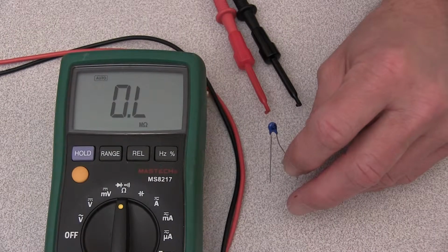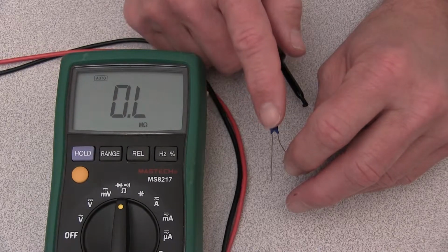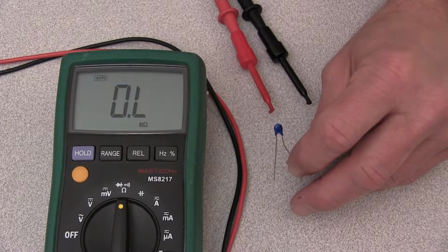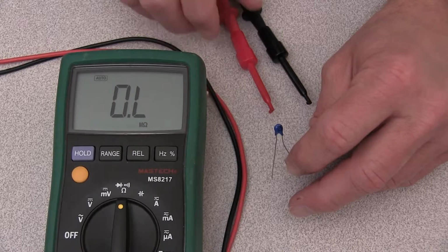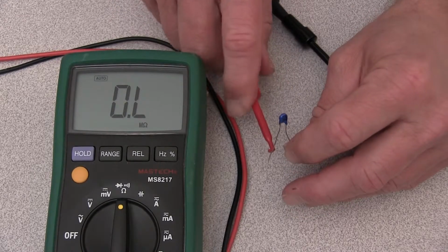This is a thermistor. If the temperature here changes, the resistance of the gauge changes. This sensor is what's called a negative temperature coefficient, or NTC thermistor. That just means that the thermistor resistance goes down as temperature increases. The first thing I need to do is characterize a thermistor. I want a range of resistances from about room temperature to the temperature of my fingers. I'll use a DMM to measure the resistance.